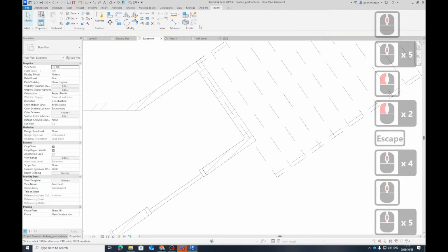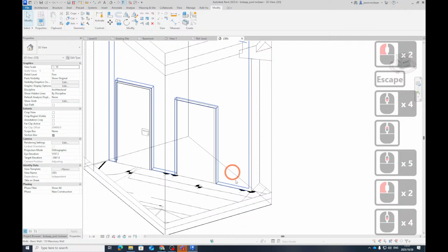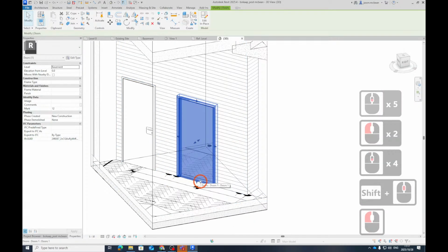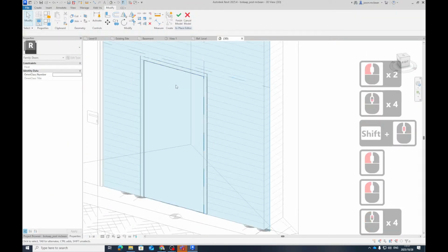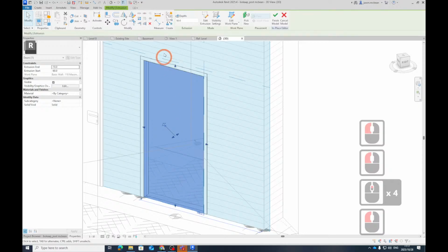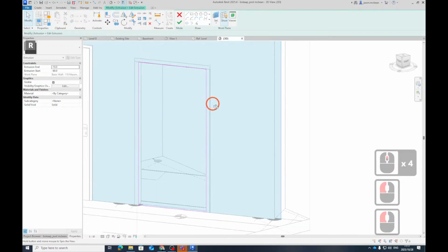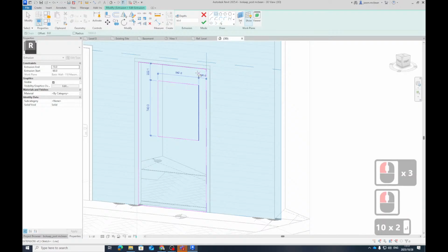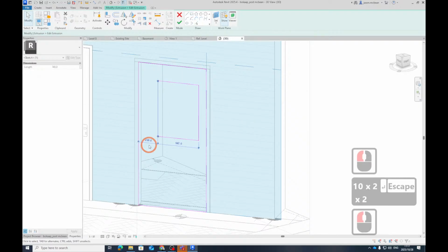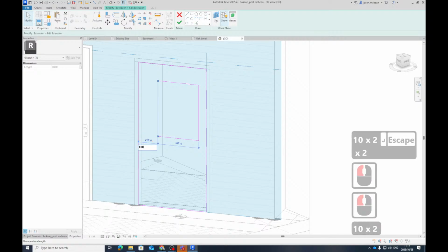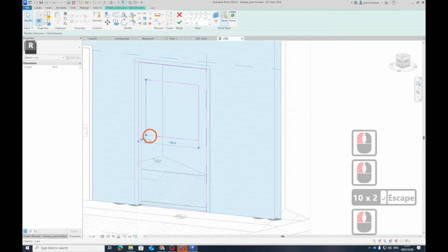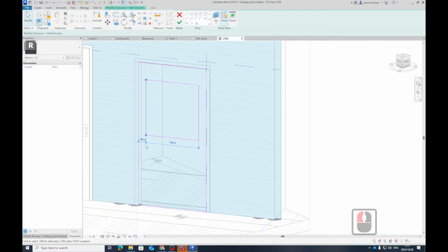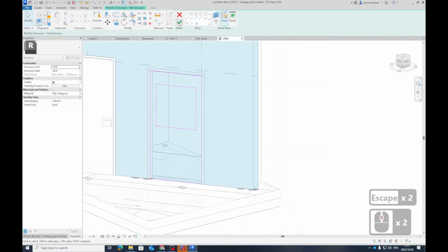Okay, for now I'm just showing you 3D view. Okay, now there's your door. Then you've got that. Now you can go and say edit extrusion again. So I'm going to go and edit extrusion again because maybe I need some glass in here. You can use dimensions to work accurately. Tab, you see, and you can make these actual dimensions and lock them so that if the thing moves, it will adjust with it. Okay, so you can make these dimensions. Finish.